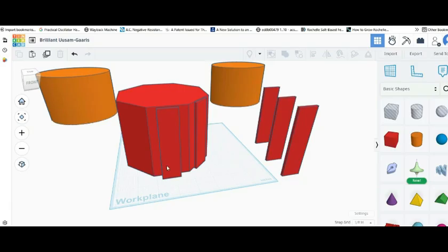Down, then you got to go underneath the rotor, around the axle, back to here, up, around, and then you do the same thing for another coil here, and another coil there. And the problem that makes it very complicated is you're going around the axle, over, then under, and then you got 3 of them. So around the axle, there's a big mess that you gotta be very careful with.